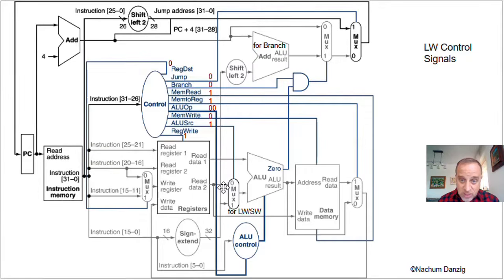It hasn't yet reached the ALU, but the output of these lines will be whatever the RS is here and the RT is here. The RD is still kind of irrelevant because we didn't get data to write yet. But this RS and RT have produced outputs over here, which we're going to need. Also, the immediate value has become sign extended to become a 32-bit value.